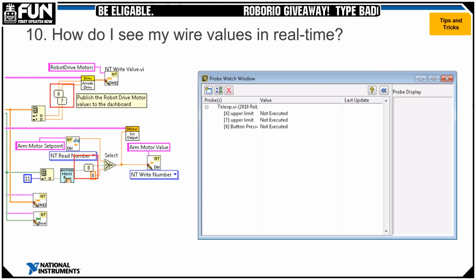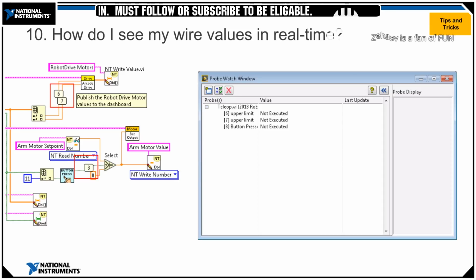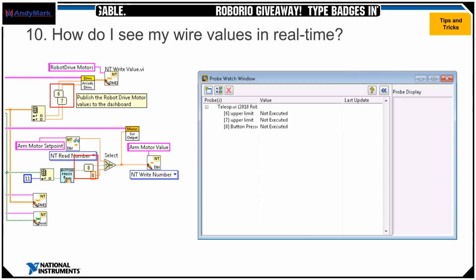If you want to be really specific about getting your data in Autonomous, you could also put poll robot data or poll game data there. I would suggest putting it in periodic tasks, putting it in its own 20 millisecond loop, and putting that data to a global data variable that you can make. In robot global data is the VI name. That's going to be the best way to get that data anywhere else in your project.